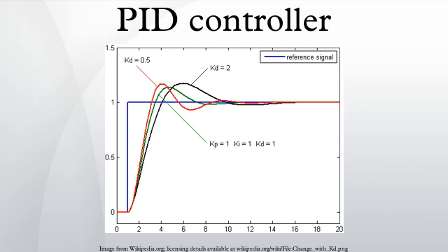Droop: because a non-zero error is required to drive it, a proportional controller generally operates with a steady-state error, referred to as droop. Droop is proportional to the process gain and inversely proportional to proportional gain. Droop may be mitigated by adding a compensating bias term to the set point or output, or corrected dynamically by adding an integral term.